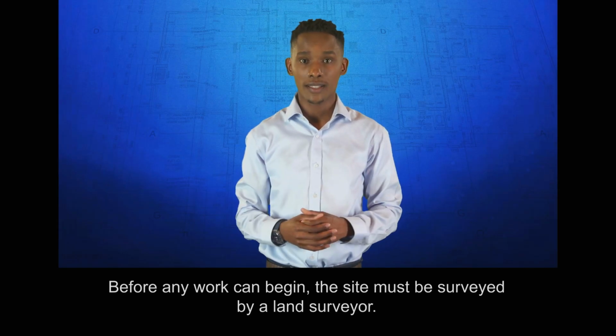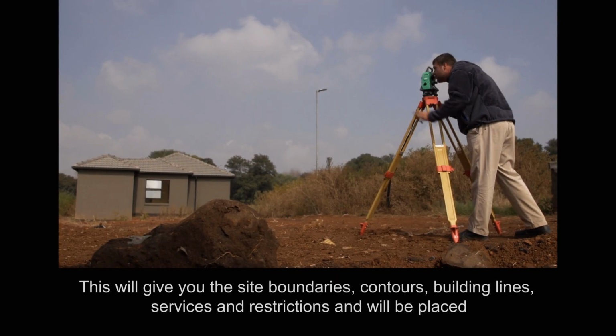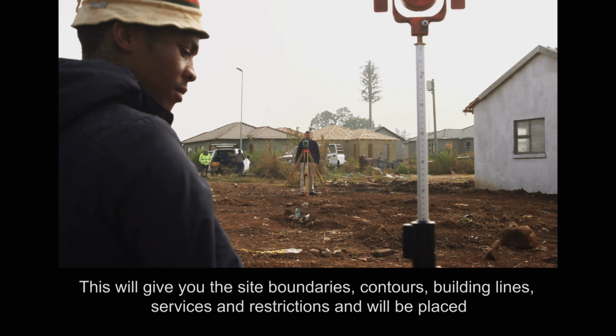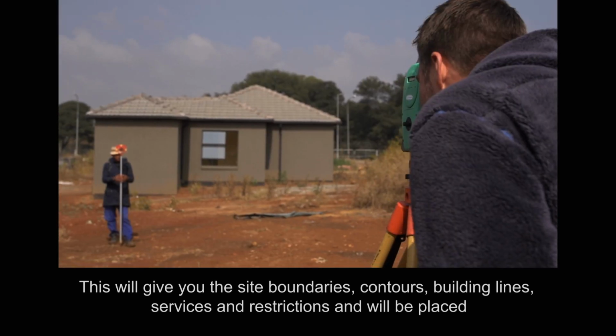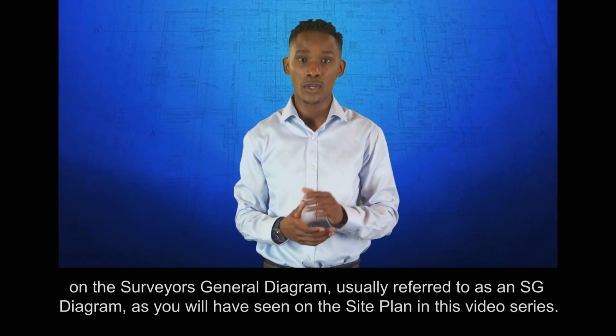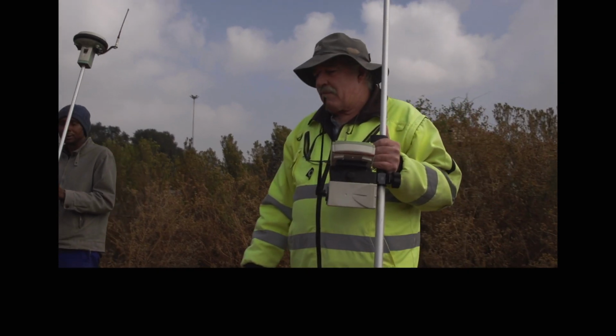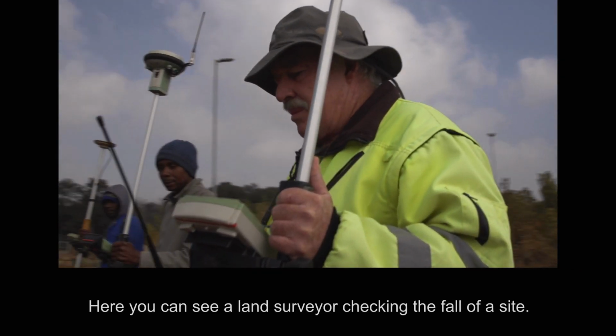Before any work can begin, the site must be surveyed by a land surveyor. This will give you the site boundaries, contours, building lines, services, and restrictions, and will be placed on the surveyor's general diagram, usually referred to as an SG diagram, as you will have seen on the site plan in this video series. Here you can see a land surveyor checking the fall of a site.